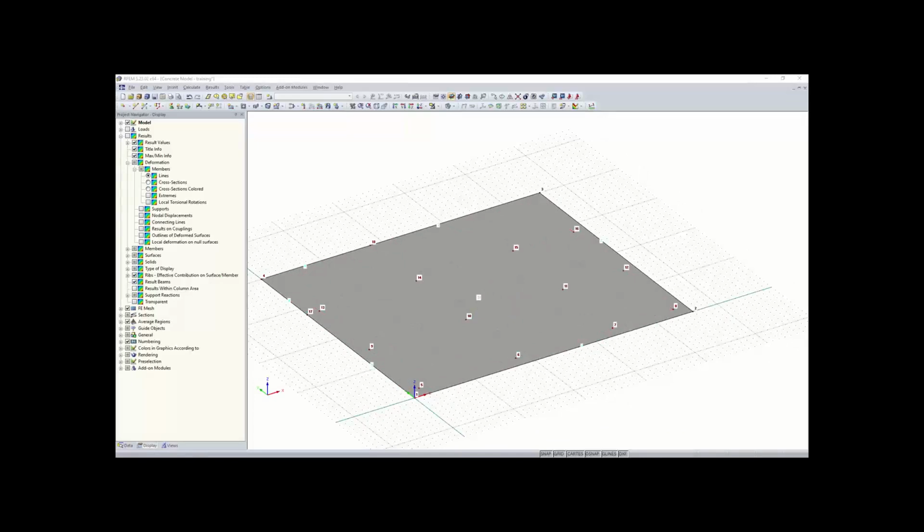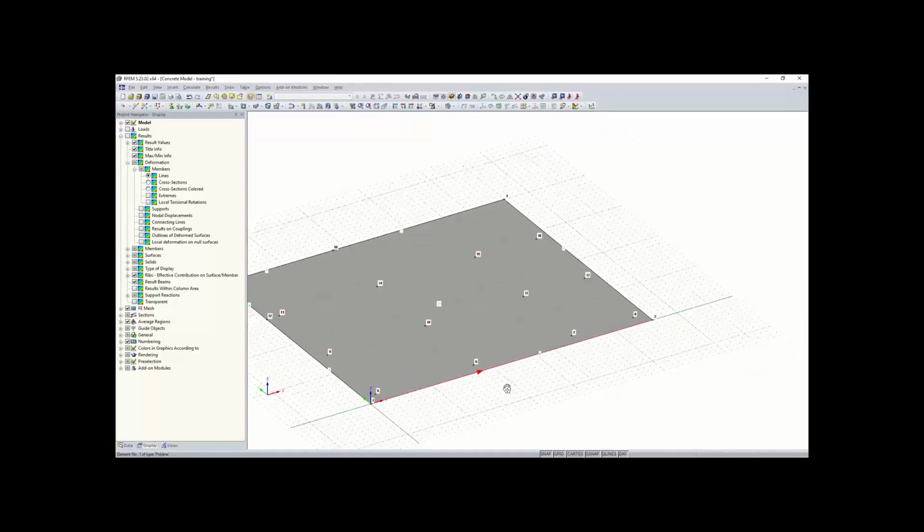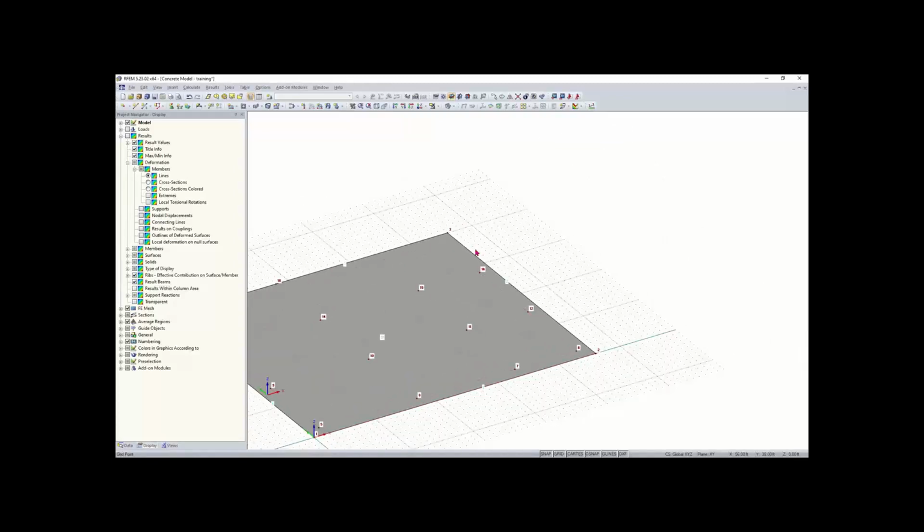Now what we can do is move on to creating our semicircle surface, which is going to be used for our spiral staircase over here. And we can go up here to new rectangular surface. And instead of clicking this, we can hit this drop down button here. And you can see we have a list of different shaped surfaces, along with being able to do a polygon, or you can select the boundary lines of something and create a surface as well if you don't see the shape here.